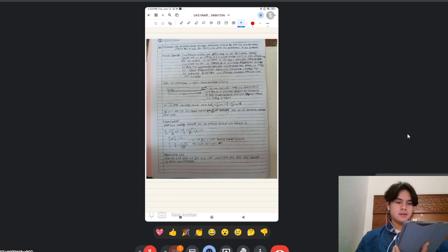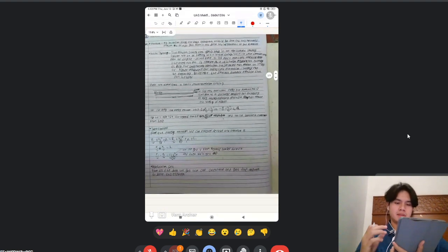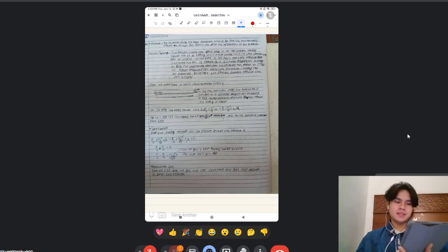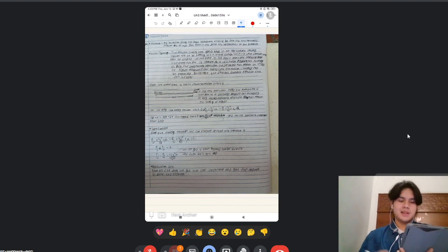The initial thinking is that the problem states that spray heads in agricultural spraying systems are to be supplied with water through 500 feet of drawn aluminum tubing from an engine-driven pump in its most efficient operating range. The pump output is 1,500 GPM at a discharge pressure not exceeding 65 psig for satisfactory operation. The sprinklers must operate at 30 psig or higher pressure. Minor loss and elevation changes may be neglected. Determine the smallest standard pipe size that can be used.